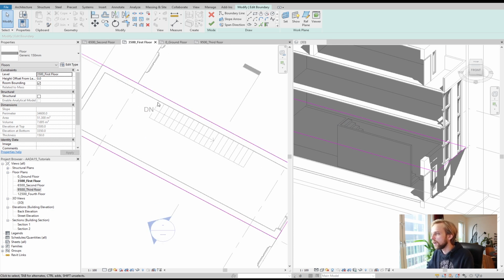And instead, let me draw out the opening for the staircase. The ceiling height is 3.5 meters. So that means if we climb up to the half of the stairs, it's 1.75 meters of clearance. That's not good. That means we need at least 3 more steps for the clearance to be okay, so that we don't bump our heads.